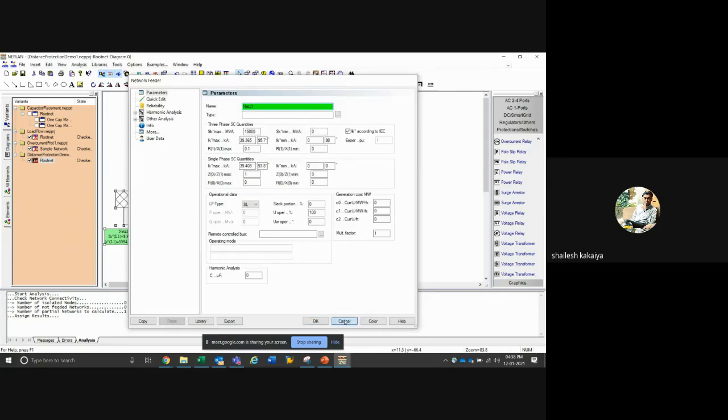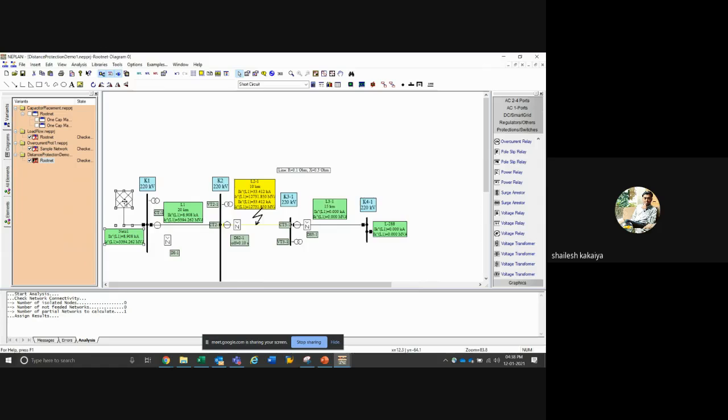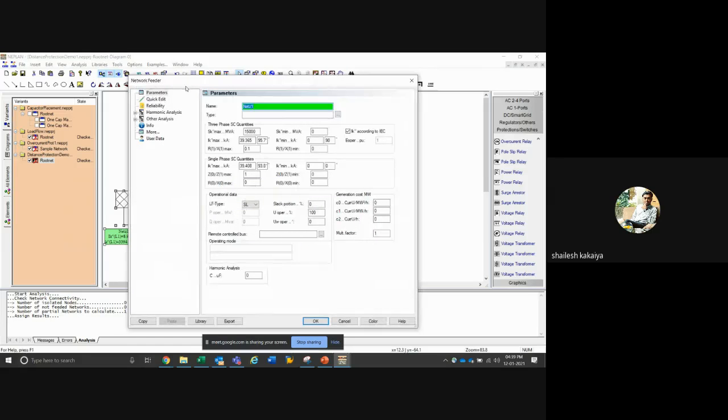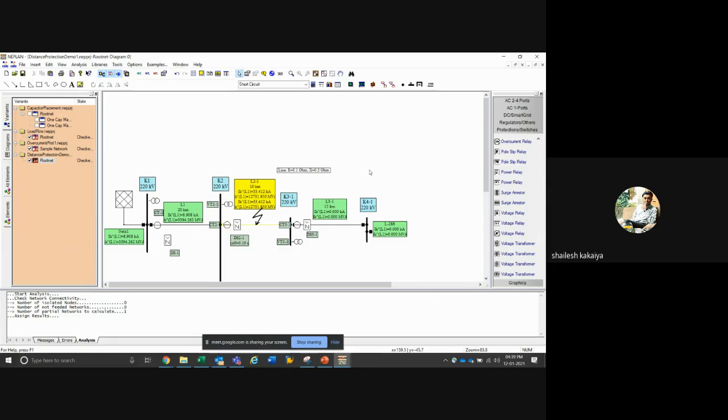Whatever equivalencing source we are doing can be taken as a network feeder element, and here we can feed the phase angles and the slack proportions, etc. From the protection point of view, whatever data you're getting, you can verify the data by looking at the response of the network in dynamic simulations.